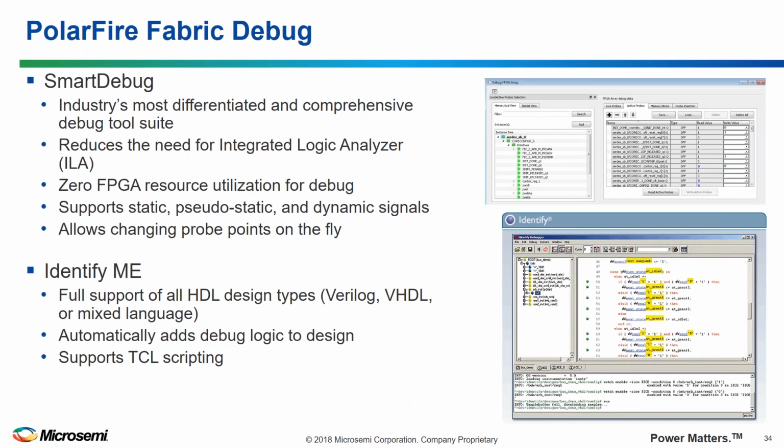After programming, you can plug in your board, and hopefully everything works, but sometimes it doesn't. If it doesn't, you need to start digging in and doing some debugging. And here we've got some tools to help you out as well. We have a tool called SmartDebug. It's a Microsemi tool that really helps you debug your device and get it up and running quickly by taking advantage of some features that are built into the silicon in PolarFire. The great thing is that these features built in for debug in PolarFire don't require any FPGA resource usage.